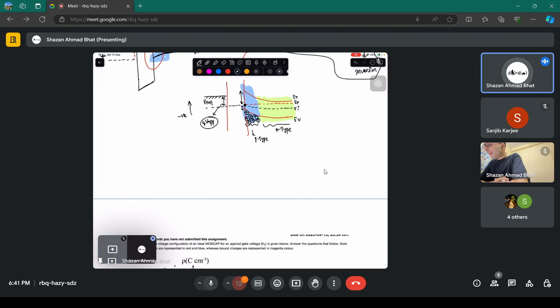Okay, because you have depleted those electrons by applying the positive voltage here and negative voltage here. All those electrons you have taken out from the system and deposited over here on the metallic side. Because on the n side of the semiconductor, you had positive ions and excess electrons. So you take away these electrons. Whatever remains is this particular depletion charge.